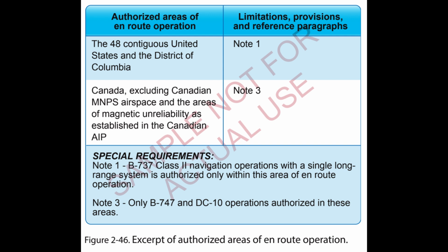Figure 2.46. Off-airway routes predicated on public navigation facilities and wholly contained within controlled airspace are published as Direct Part 95 routes. Off-airway routes predicated on privately owned navigation facilities or not contained wholly within controlled airspace are published as Off-airway Non-Part 95 routes. In evaluating the adequacy of off-airway routes, the following items are considered: the type of aircraft and navigation systems used, proximity to military bases, training areas, low-level military routes, and the adequacy of communications along the route.